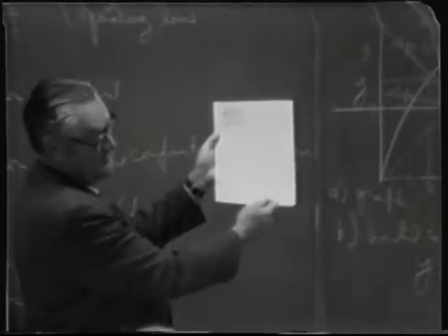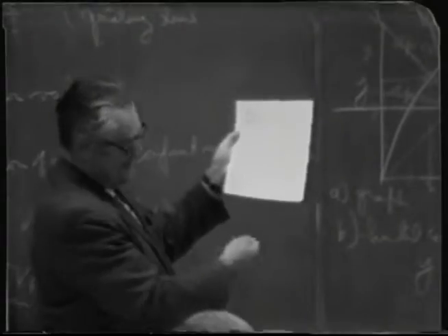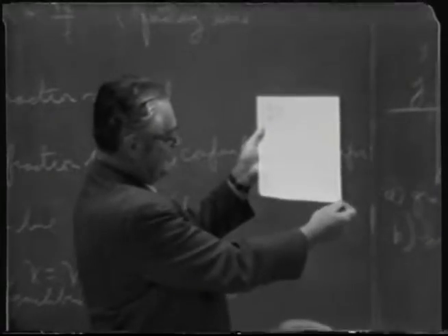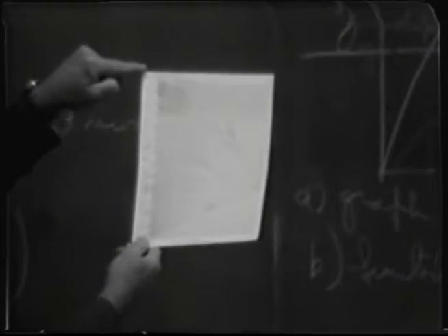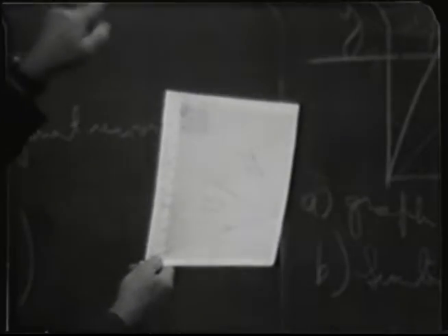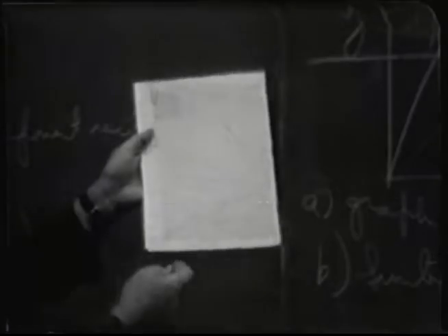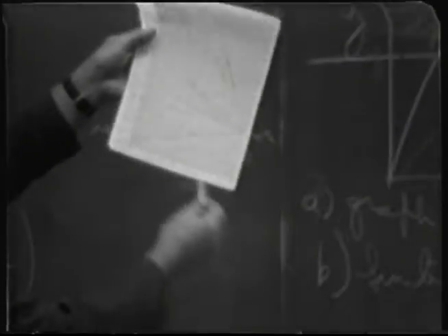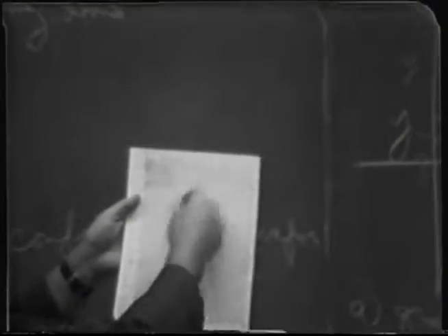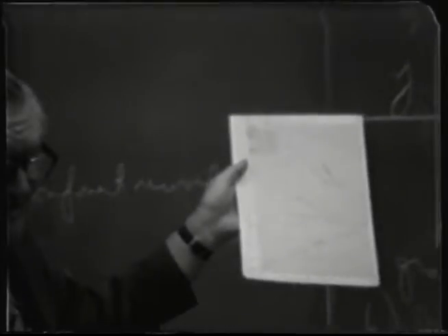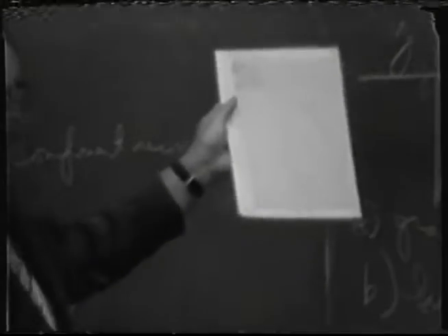In fact, I extended it a little beyond the graph paper here in order to make it work. 20% here. You need up to about 60%, or a little about 65% on the vertical scale. So I used a different scale vertically and horizontally. This is the x equals y diagonal here. So you plot 4 or 5 values of weight percent here and draw a curve through it. That's the equilibrium curve.